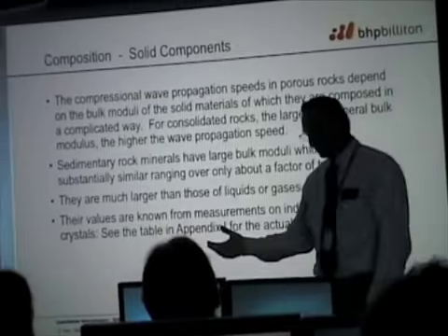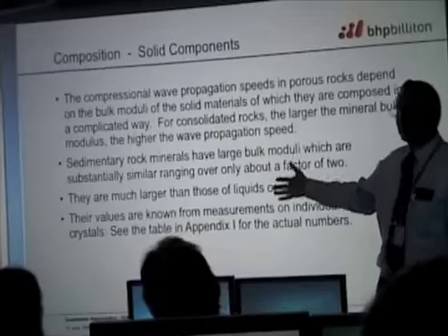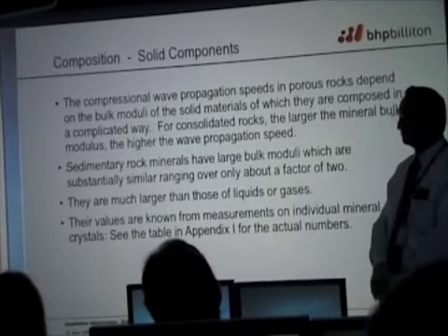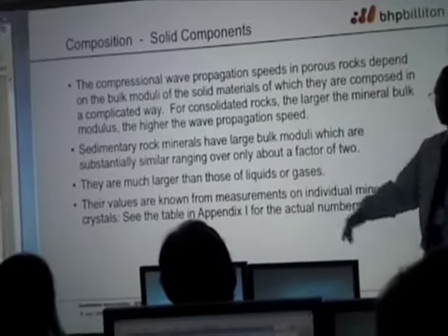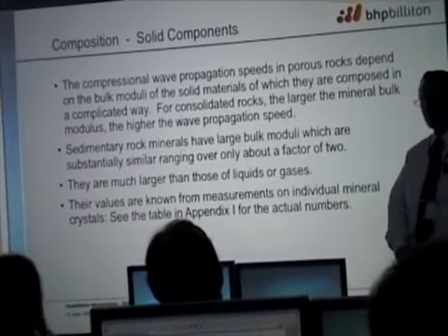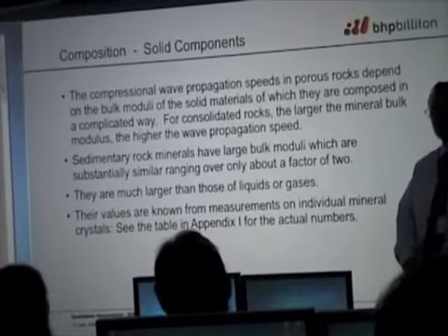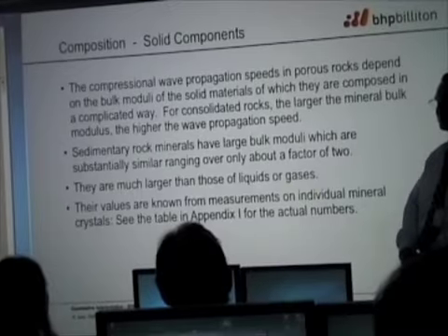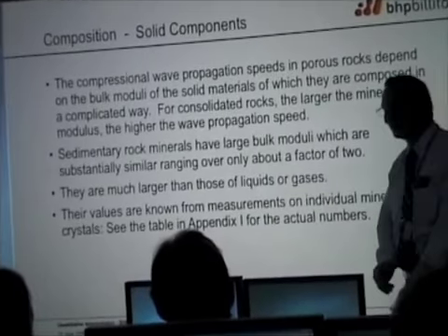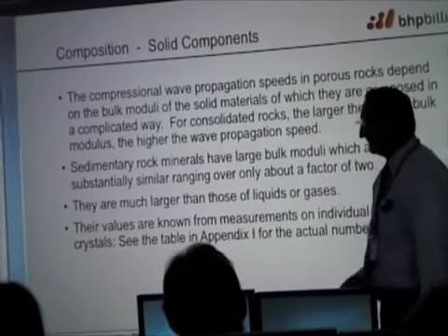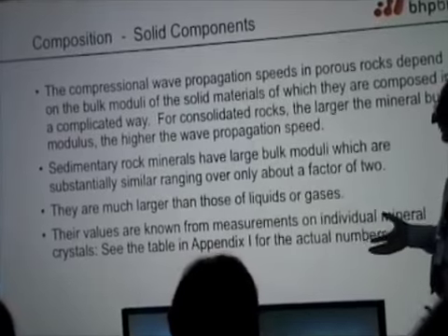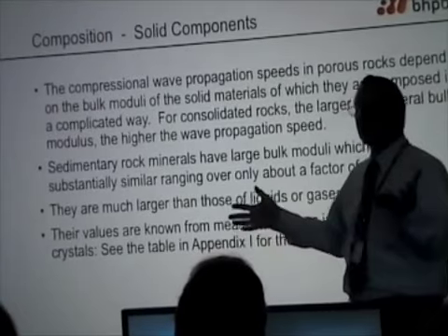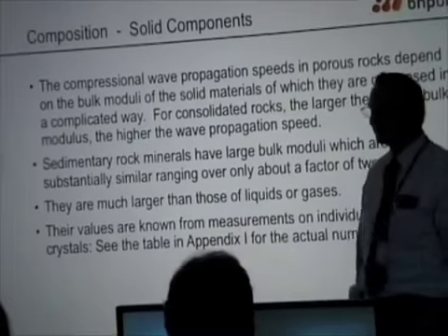I talked about compressibilities before, bulk moduli here. You'll see slides that I'm going to talk to you about, with those 10 to the 10th dynes per square centimeter. I use CGS units, which are not very popular these days, but since I'm an old fogey, that's what I use. What does that mean? Silicon dioxide has a bulk modulus of something like 38 times 10 to the 10th dynes per square centimeter.